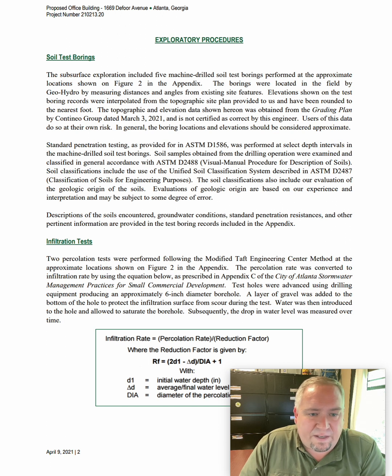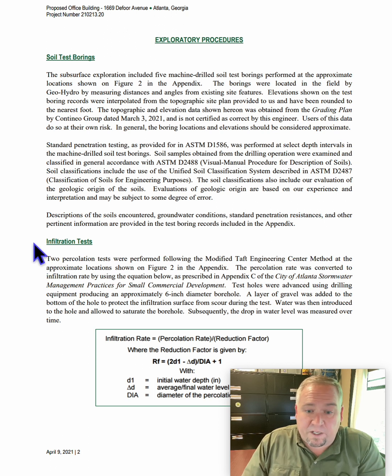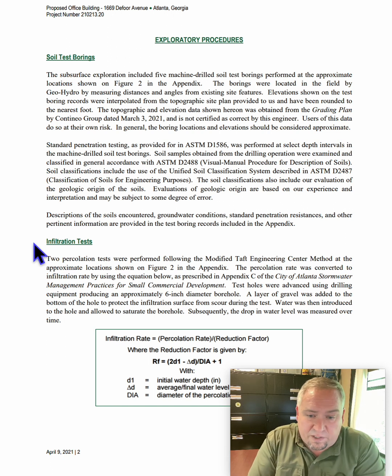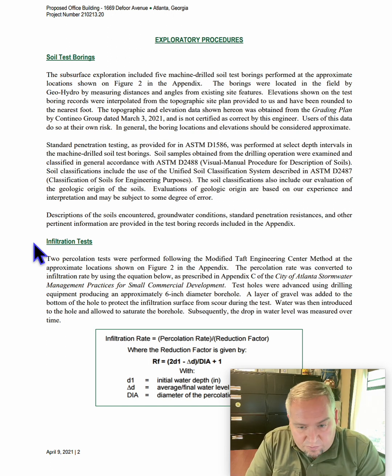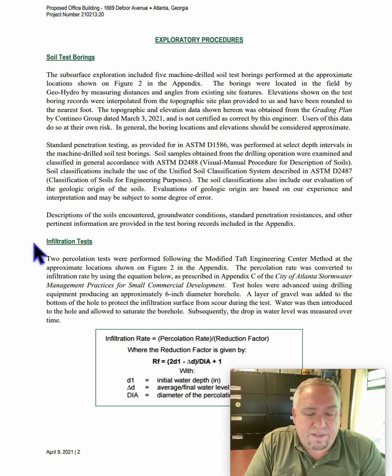Down here, you'll have infiltration tests. So you're looking at percolation. Percolation is, if I was to pour a cup of water on here, would the water just sit on top of the dirt, or would it absorb down in there like beach sand? Or would it be like clay and just sit there like a little pond? All these factors matter. They tell you what's below the soil.